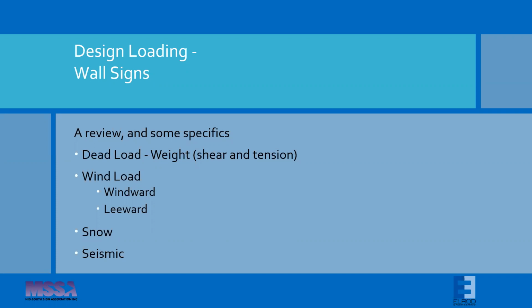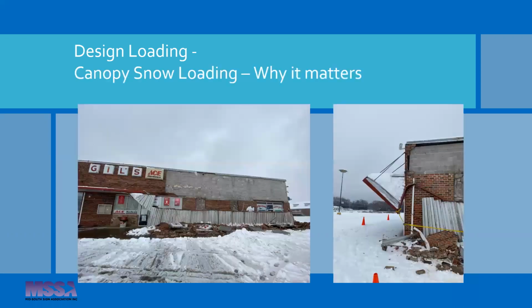As I mentioned, this is typically where we get the most pushback from sign companies when we have to consider snow load, because a lot of times it doesn't make sense from just walking around outside that snow could be significant, but it really can. Seismic loading typically doesn't control, but it might. It's just something to be aware of. It's not as prevalent in the South unless you're over in West Tennessee, Eastern Arkansas, but there are things to be considered. And again, your engineer should be aware of this kind of stuff.